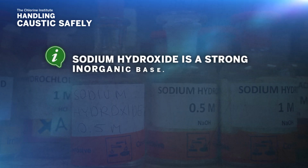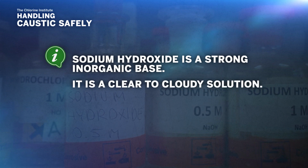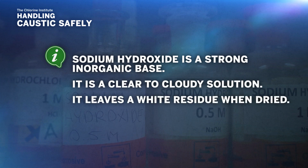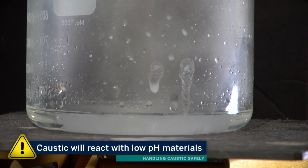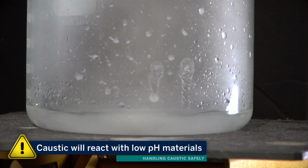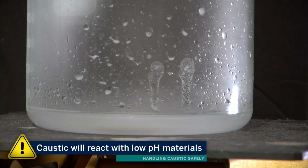Sodium hydroxide is a strong inorganic base. It is a clear to cloudy solution. It leaves a white residue when dried. Caustic will also react, sometimes violently, with low pH materials. Mixing strong acids, for instance hydrochloric acid, with caustic will generate large quantities of heat, causing the mixture to splatter.